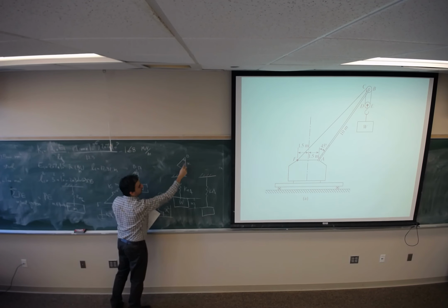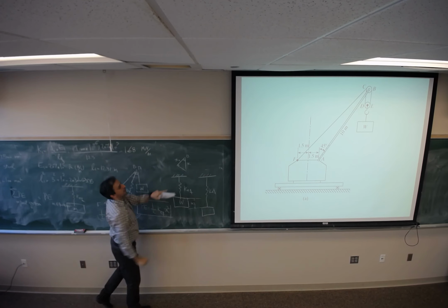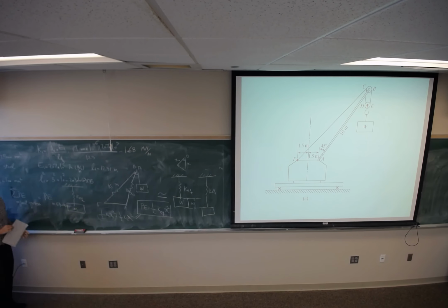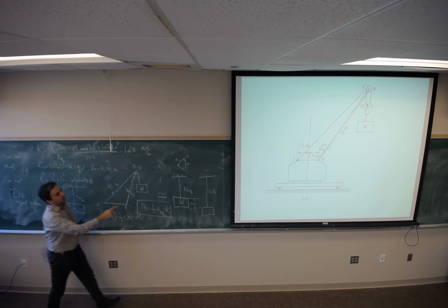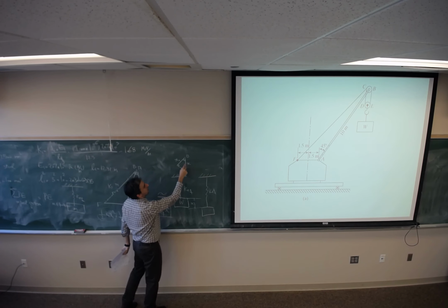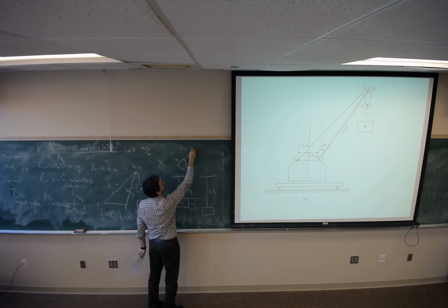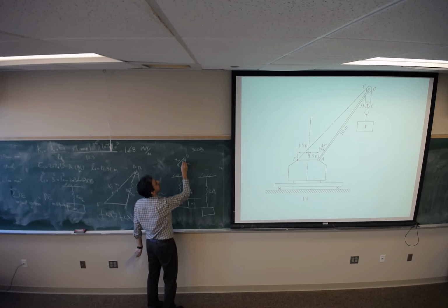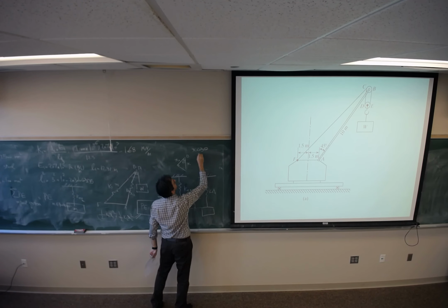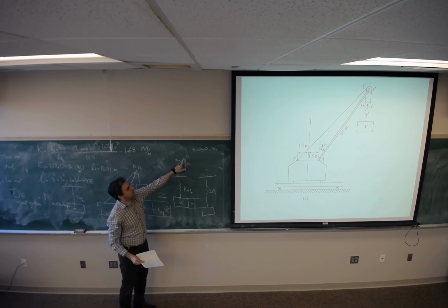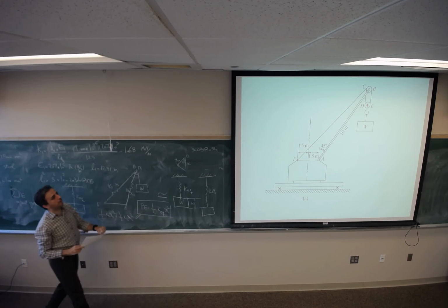So if this is 90 degrees, the compression is going to be this, which is X1. So if this is the X, the compression that I'm going to make on BF would be X1. Here I can find the relation between X1 and X. X cosine of theta would be X1. Cosine of theta is going to be X1 divided by X. If I multiply cosine of theta by X, I will find X1.